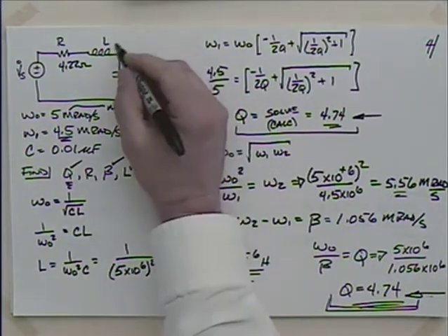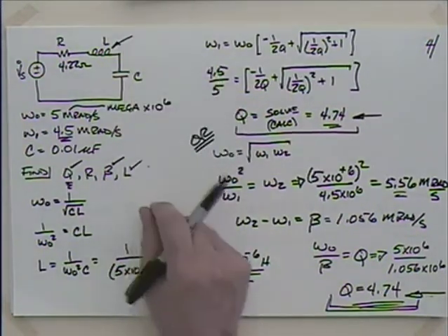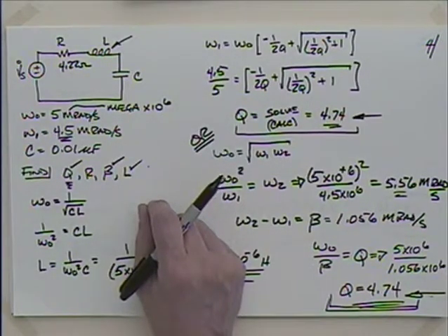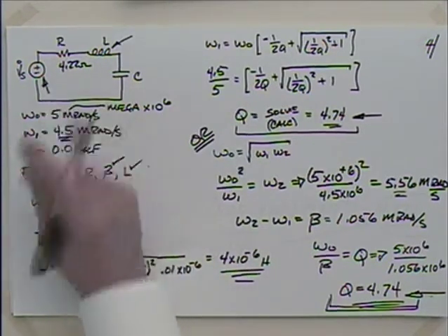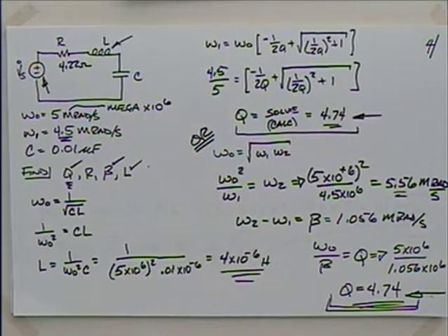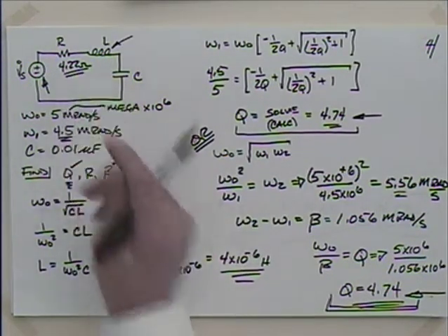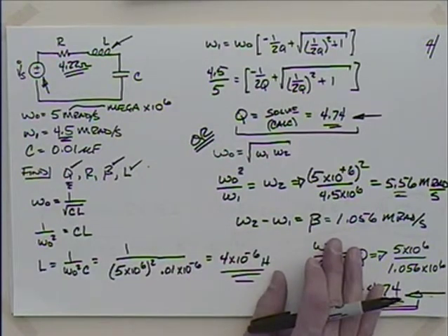What'd you come up with for the resistance in your inductor? It was probably 60. If we had a bigger inductor, it could be a lot larger. I mean, we had inductors on that same board that were, what, 600 ohms? And what about the function generator? What resistance did we have there? Another 50? Okay, so that begins to kind of spoil the fun at 4.22, doesn't it?